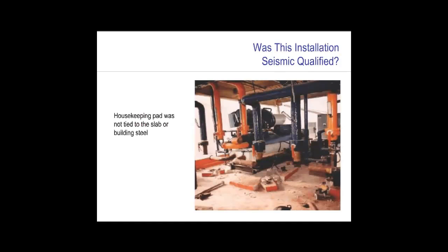Does this equipment look like it was seismic qualified? At first glance, one might assume that it was not. However, upon closer examination and research, we find that the equipment was seismic qualified. Unfortunately, the installer did not confirm the structural design of the housekeeping pad with the locally registered civil or structural engineer. Thus, the equipment became inoperable after the seismic event, not due to the lack of the equipment's seismic demand withstandability, but because of the lack of coordination and confirmation of the structural elements involved.